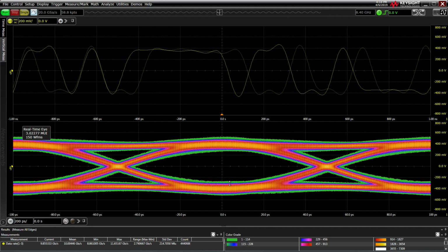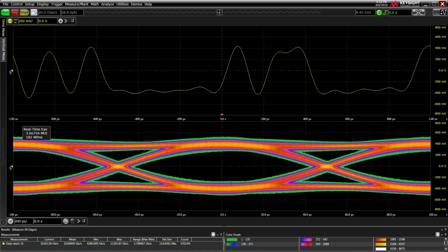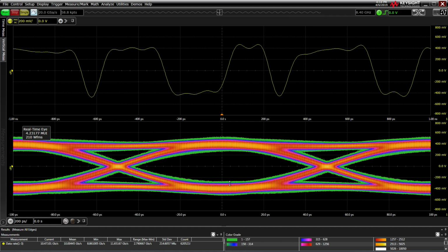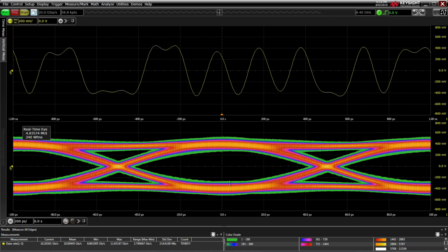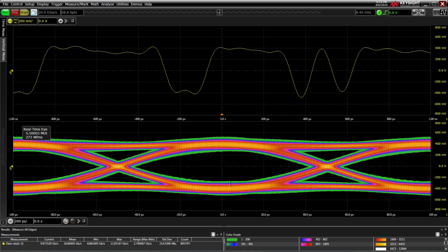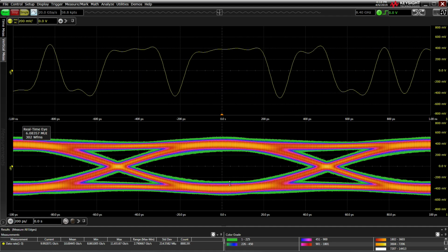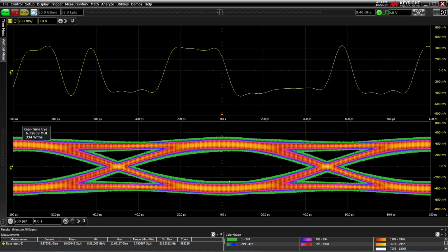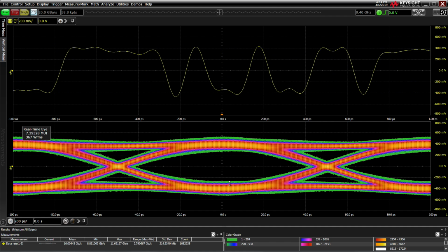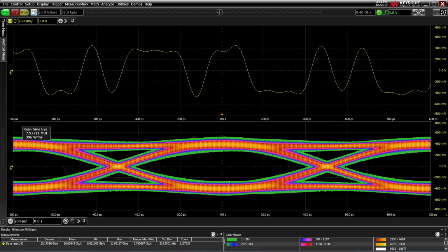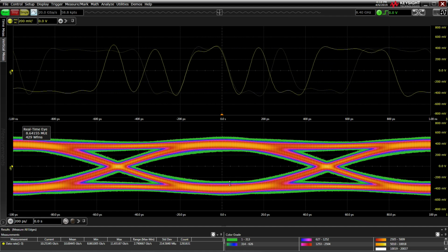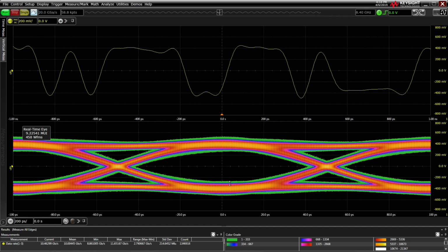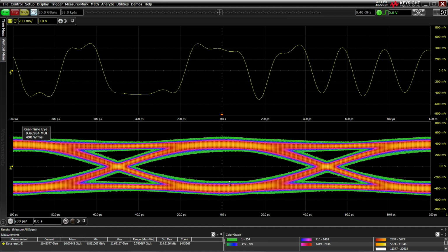So I know that the signal is being generated, and that's very important. And now we need to find out if that jitter port is actually working or not. The easiest way to find out is to add some signal into it at a much lower baud rate where the jitter is completely clean, because there's no ISI, there's nothing. You're going to get a nice eye crossing, and then we can see if our own jitter switch that I added is working at all.